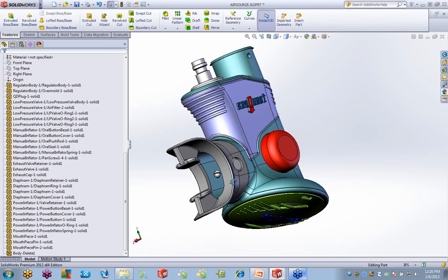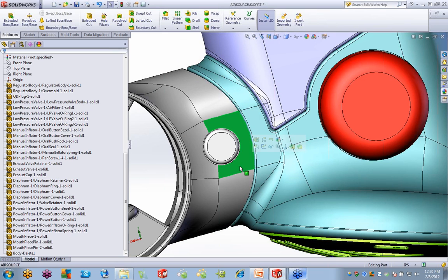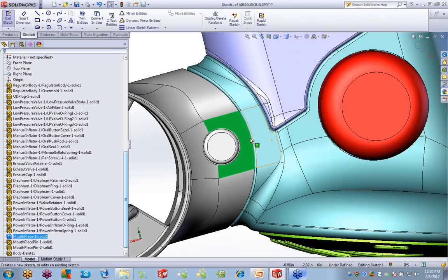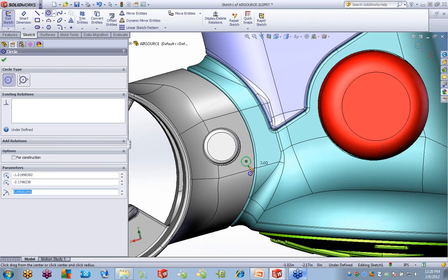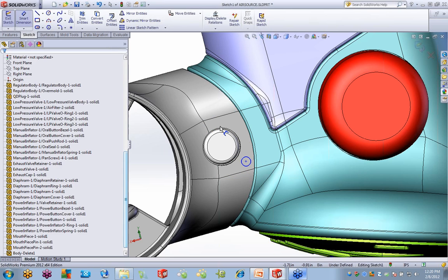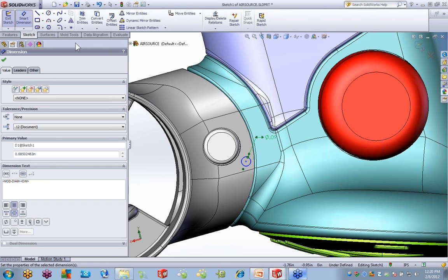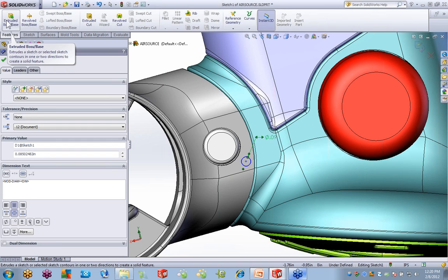Let's say I wanted to put a small hole feature in through the parts. Now, when I'm in a part file, I don't need to do edit body or any other function to continue to create or affect the solids that are here. So I can just sketch as is right within the interface and dimension as I would typically dimension. There's nothing different there. But when I actually go to create the individual feature,